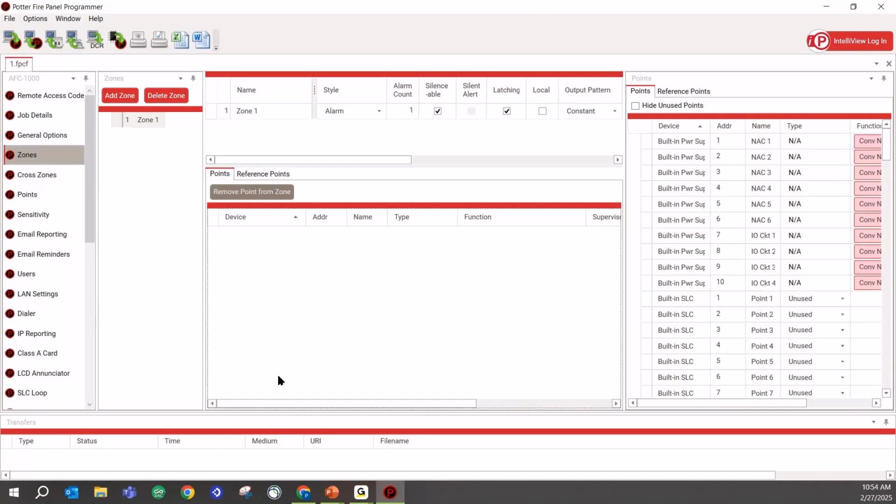Last, certainly not least, if I've got a smoke detector and I want to change it to a heat detector, I would pull down the smoke, put up the heat, and of course I'm going to have a device mismatch. Software is expecting to see a smoke. Now there's a heat. I run the learn command, and let's say that smoke detector was in 5 zones. I now have a heat detector in those same 5 zones. So please be aware of that. And we're not losing any other programming when we do those things.